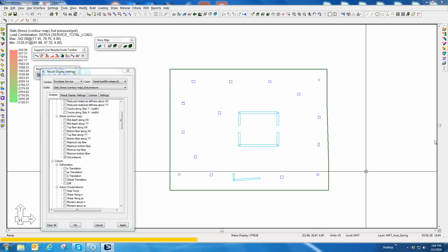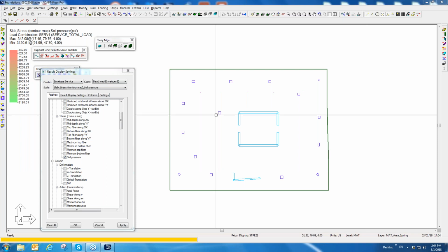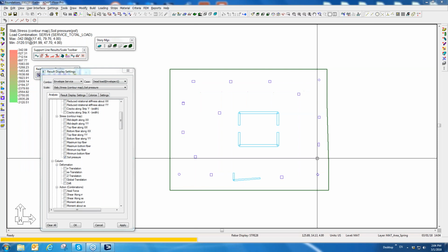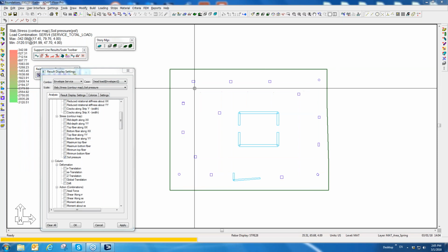Okay, so there's a punching shear question. Do we check punching shear for columns located above a pile support if ADAPT gives me punching exceeds code? If you have a series of piles, if this acts as a pile cap, essentially, do we check punching for that?